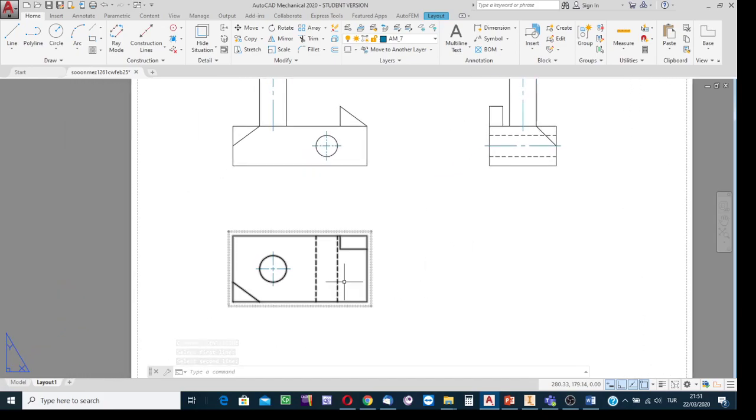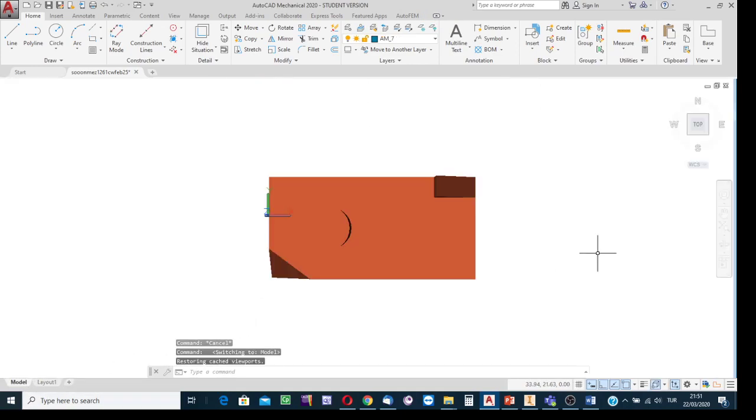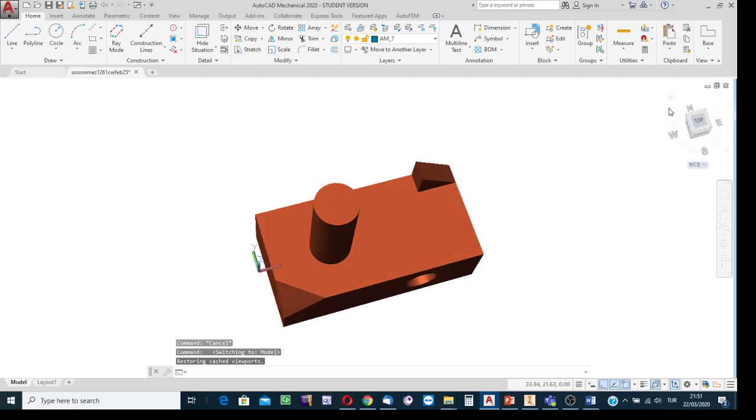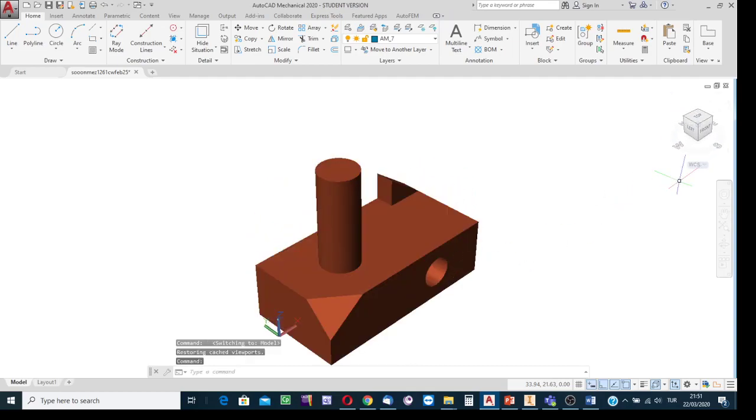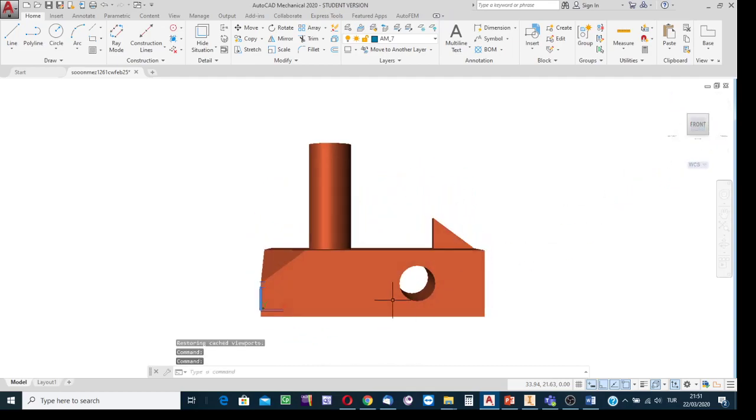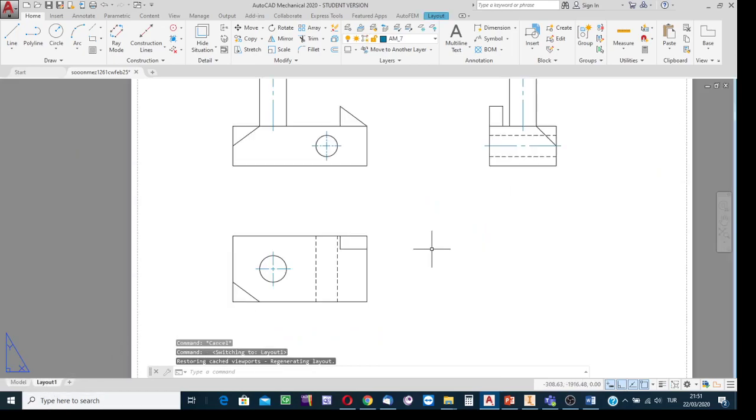On the top side view, yes, this hidden rectangle corresponds to the image of the hole. Where is the hole? In the design of the object, you see there is a hole over there. Yes, for this hole, show the longitudinal axis on its lateral side views. Center line, write the command, and then indicate the limiting lines, this and that.